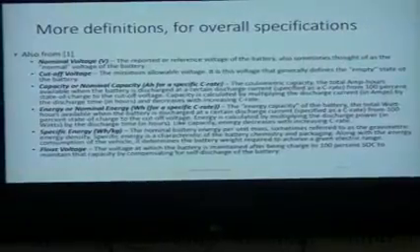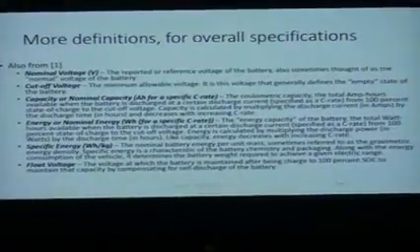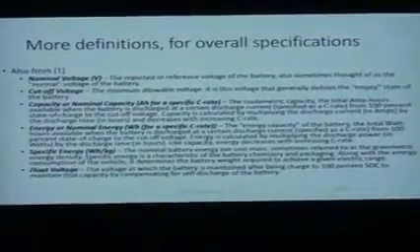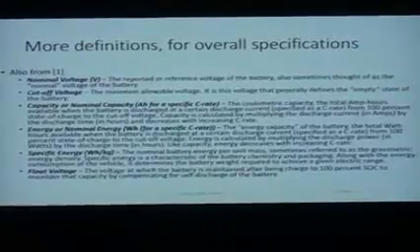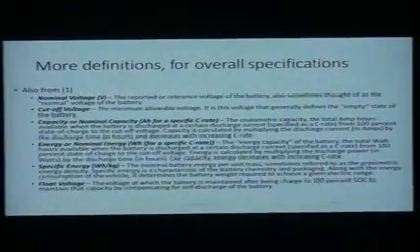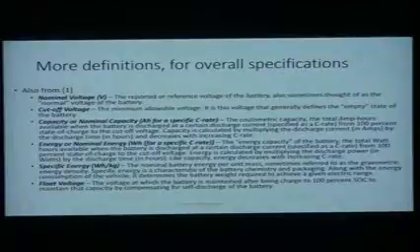Now, the capacity actually depends on the C rate that we talked about earlier, right? If you draw charge out more quickly, if you discharge your device more quickly, you will actually have less capacity, in part because of the things we talked about. There'll be more thermal dissipation, okay? So the amp hours are referenced to a particular C rate, but usually they're done in such a way that they're in the moderate discharge rate, so not really fast, where things tend to be less consistent.